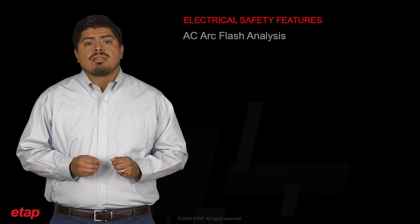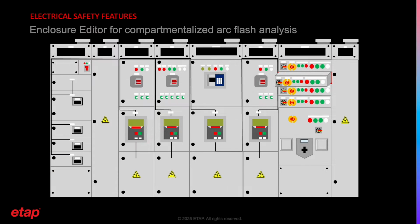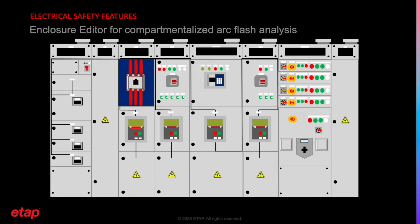ETAP also includes features that allow power engineers to perform an arc flash analysis for various types of AC systems. For example, in oil and gas applications, when evaluating low-voltage equipment, a common challenge is efficiently accounting for varying arc flash input data due to differences in equipment characteristics and typical work practices. ETAP's solution to this is the enclosure editor, which empowers engineers to perform a compartmentalized arc flash analysis. The enclosure editor can also be used to model common scenarios, such as multiple electrode configurations, within a single enclosure, to determine the worst-case arc flash results with minimal effort.